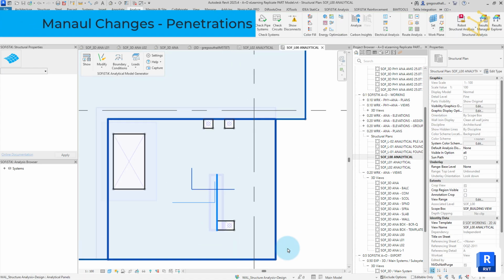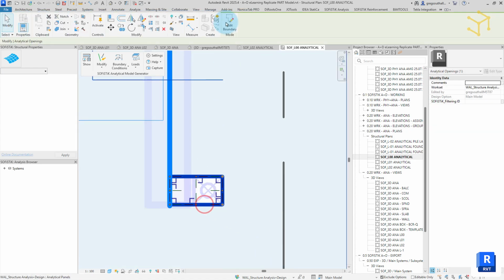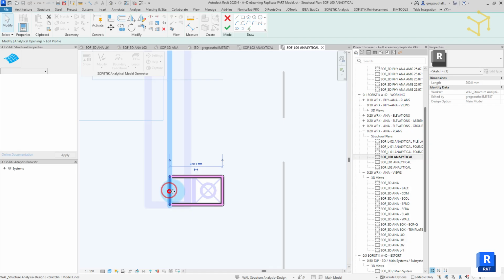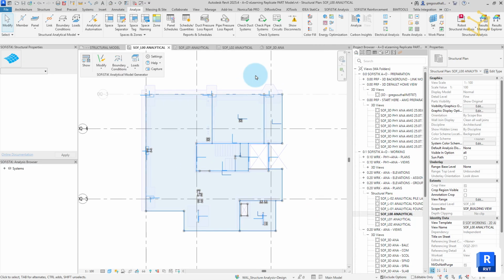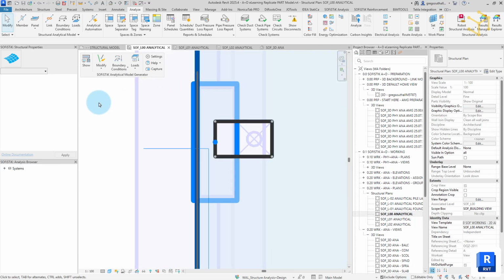There are a couple of penetrations which also require adjustment which we can address with the same boundary element tool. There is a further penetration at level 0 to address. You can see an edge is coincident with the axis of the 1D column element nodal intersection. Amending this may cause unwanted behavior. Let's try to amend and see.